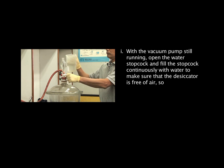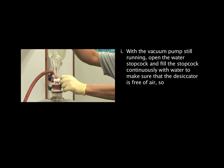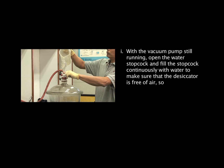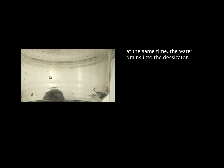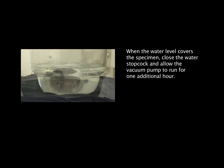I. With the vacuum pump still running, open the water stopcock and fill the stopcock continuously with water to make sure that the desiccator is free of air. At the same time, the water drains into the desiccator. When the water level covers the specimen, close the water stopcock and allow the vacuum pump to run for 1 additional hour.